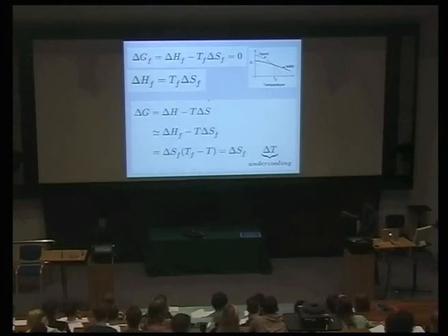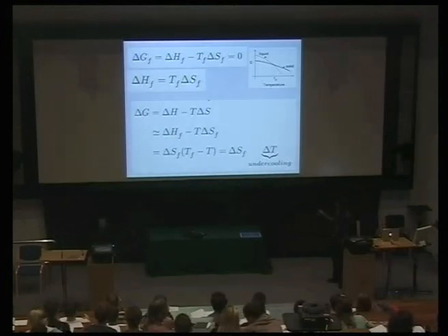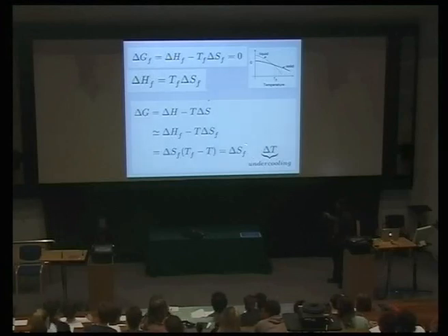So using this equation, it's straightforward to find delta G at any temperature T. And of course, we have a relationship between the enthalpy and the entropy here. So I can simply replace the entropy term by this, and therefore, I get the driving force, delta G, as a function of the entropy of fusion and the undercooling below the melting temperature.